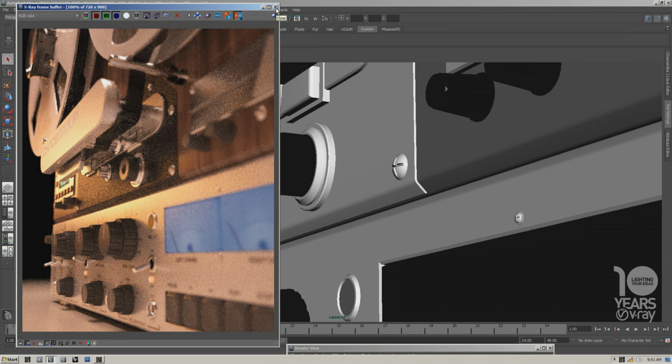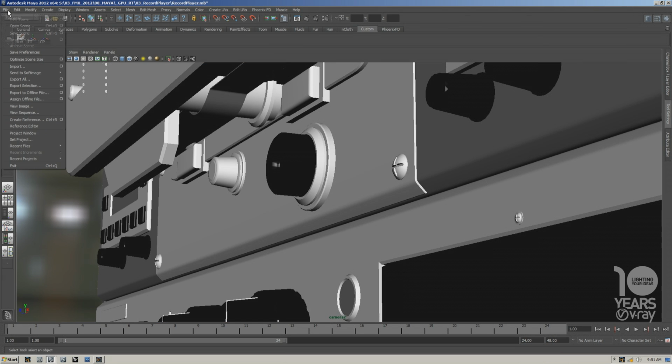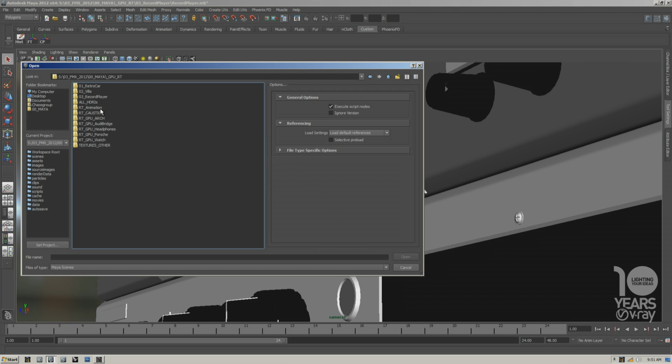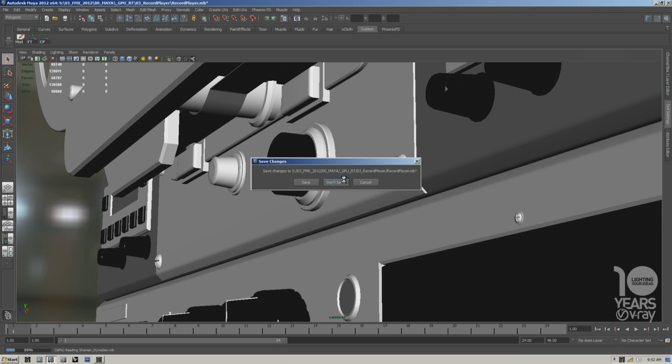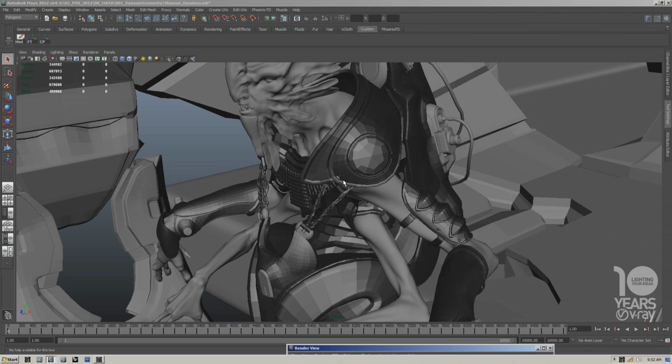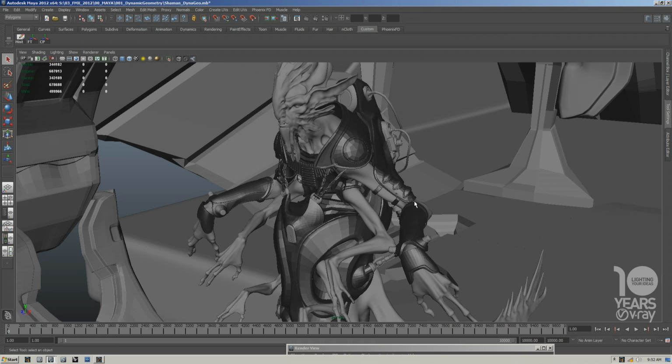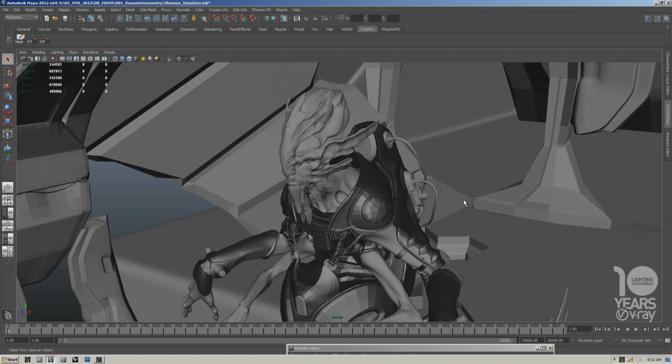So let's take a look at some options of the production renderer since we're at it. And I'll start with talking a little bit about dynamic geometry. With V-Ray, you have 3 types of dynamic geometry that you can render. The first one is render time subdividing. If you have low polygonal meshes, you can subdivide them during render time. You have displacement, and you have the V-Ray proxy. For all these dynamic geometries, the same rule applies. Only the geometry that is visible in the bucket, which is being rendered at the moment, will be loaded into the RAM of your computer. So using dynamic geometry with V-Ray is extremely fast and extremely memory efficient thanks to this algorithm.